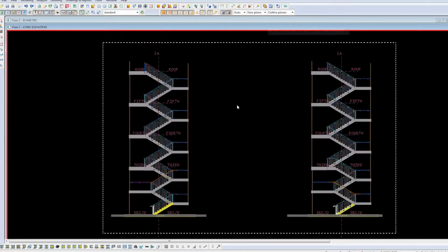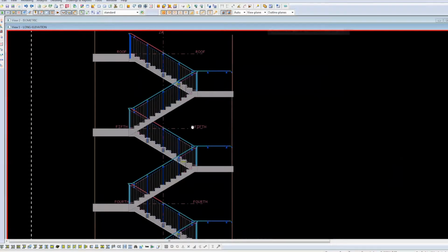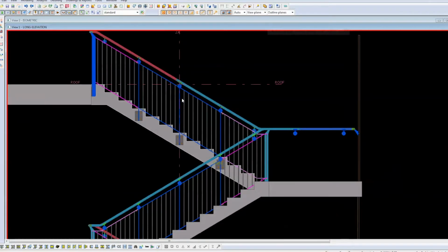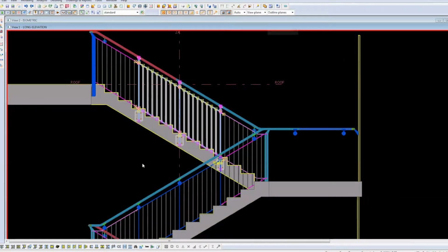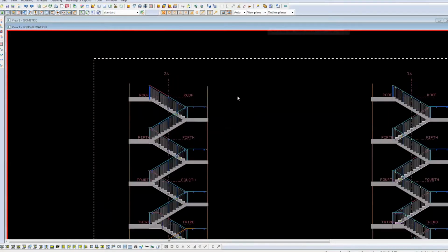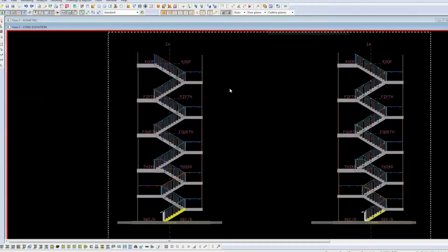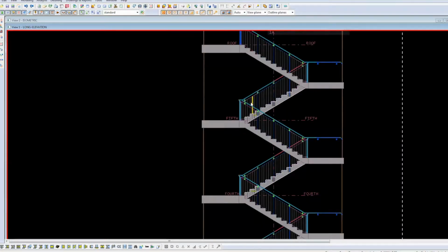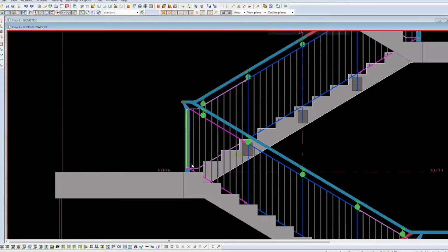These are the two stairs that I've recently been down to measure up and detail for the client who sent me the badly modelled balustrade to the 4 staircases. So I've adopted the same principle where you've got a mid panel which is copied in these 2 staircases. By the time I'd done my justification, which I'm going to get into in a second, this mid panel was the same for this entire stair. This is an opposite end stair, so basically that panel got repeated for every flight, and then you just get variations at the ends, mainly due to the fact that the void lengths vary.